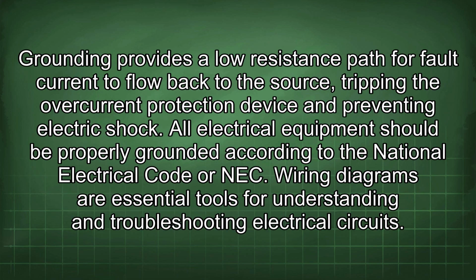Grounding provides a low-resistance path for fault current to flow back to the source, tripping the overcurrent protection device and preventing electric shock. All electrical equipment should be properly grounded according to the National Electrical Code or NEC.